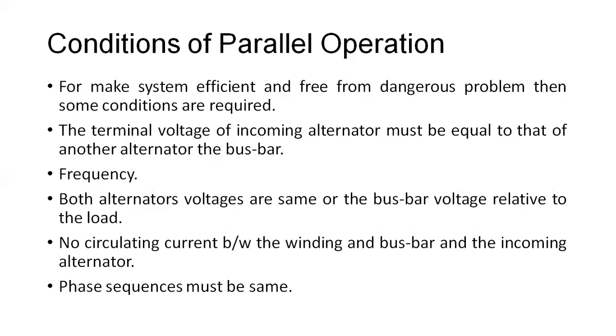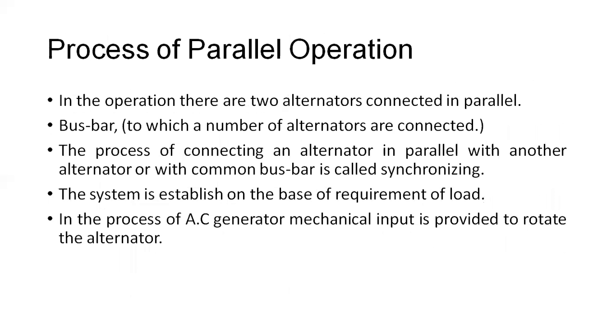It's very important. And the last, phase sequence should match. Means RYB or ABC will be similarly connected with this ABC. We cannot connect it with A to B and B to C. Not like that. The A phase should be connected with the same phase. The phase sequence should be matched, that is the RYB sequence, clockwise or anti-clockwise, whichever way you are able to remember.